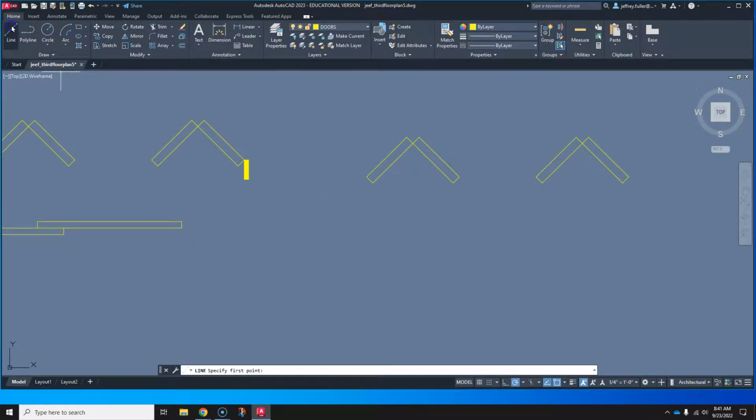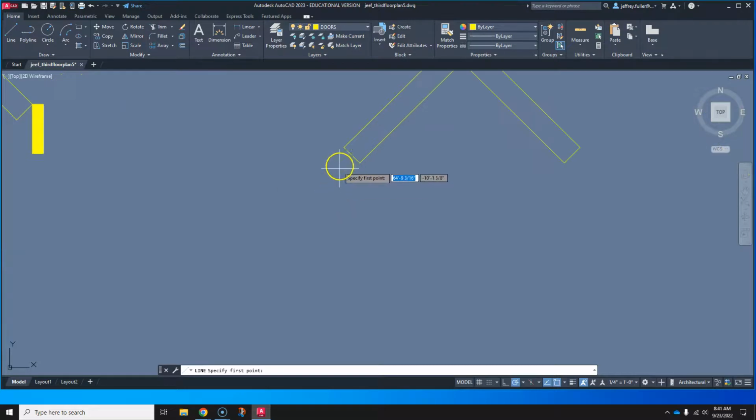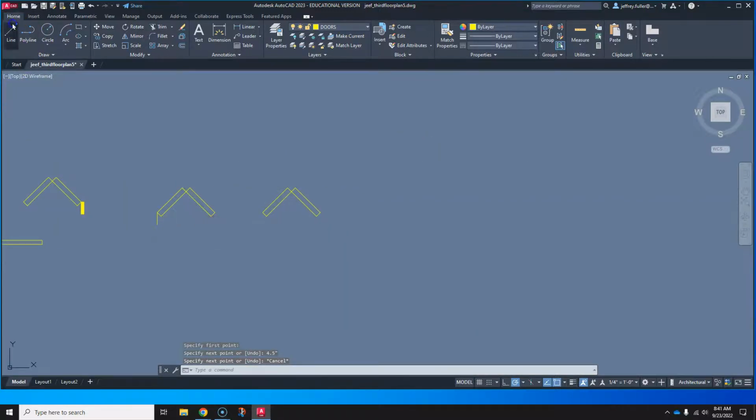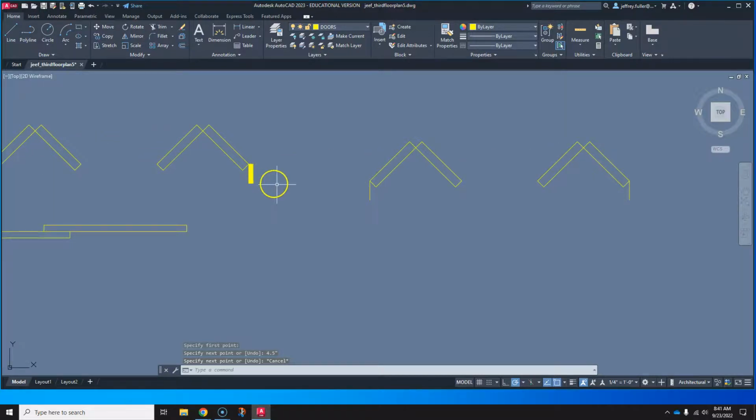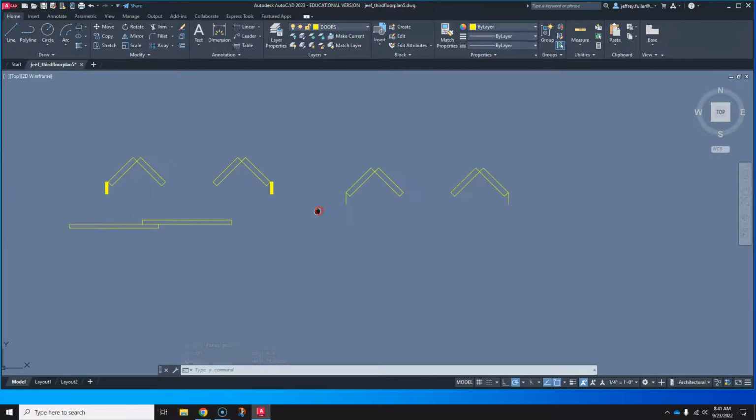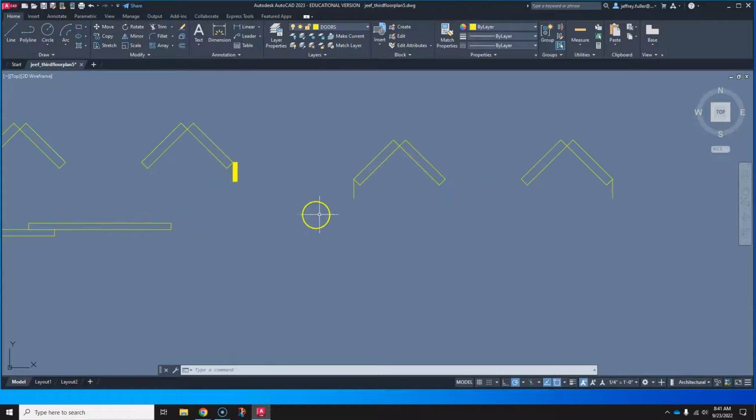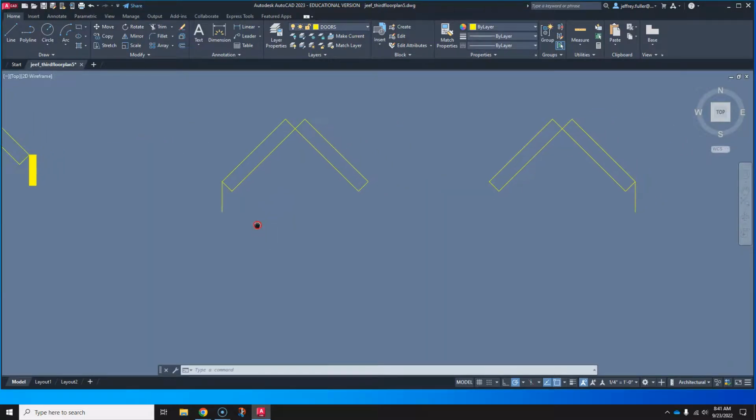And I'm going to do that right here from this corner. So I'm going to grab the line tool again, and I'm going to click on this corner. That's where they're going to connect to the wall. And I draw them according to my wall thickness. And we've already established that our wall thickness is 4.5 inches. Okay, draw another one at 4.5 inches. Okay, now I want to thicken those up a little bit to make some framing, to make sort of like a door frame.